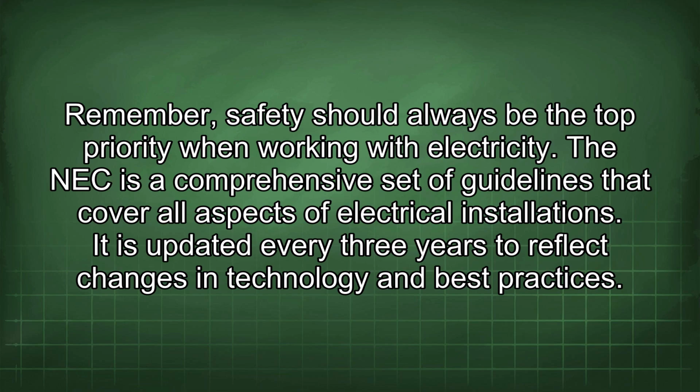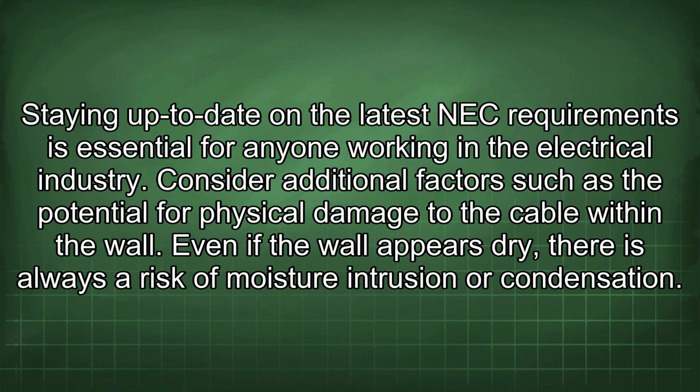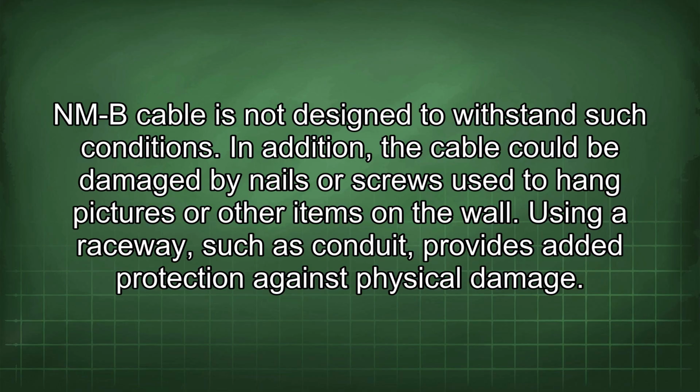It is updated every 3 years to reflect changes in technology and best practices. Staying up to date on the latest NEC requirements is essential for anyone working in the electrical industry. Consider additional factors such as the potential for physical damage to the cable within the wall. Even if the wall appears dry, there is always a risk of moisture intrusion or condensation. NMB cable is not designed to withstand such conditions.